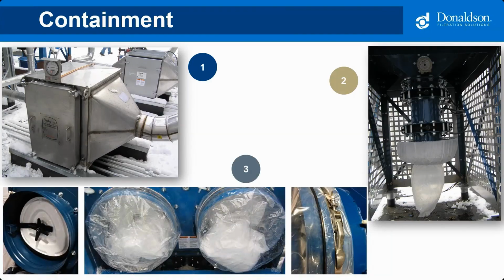Typically, this is after the airstream has gone through the dust collector, clean air discharge from the fan, and then it goes to a secondary after filter, which is typically a HEPA or greater rating. It's going to capture those fine particulates that either get through the filter media, or it's a secondary fail-safe if you develop a hole in a filter or something like that. The after filter is there to prevent it from going back into the building.